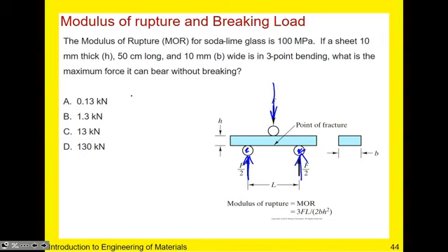So if you have, let's say, a bar of alumina or a bar of silica, or here soda lime glass, if we know the dimensions, we can calculate the MOR by just using this convention, where it's just 3 times the applied force times the length of your material divided by 2 times the thickness and also the height squared. And so you can calculate the amount of force that a material or ceramic can withstand before it fractures.